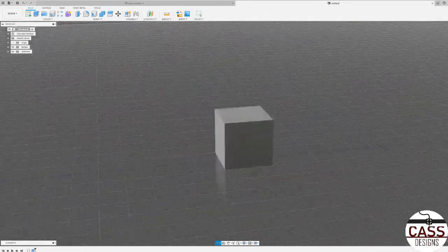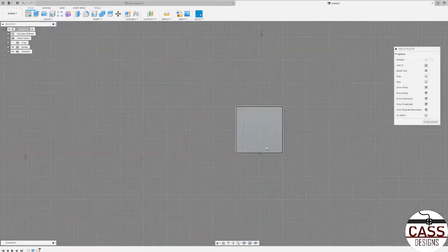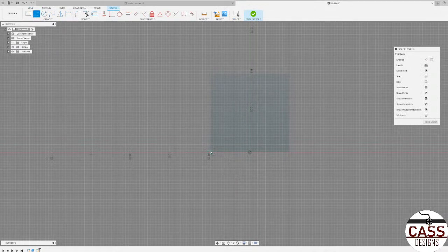So usually keycaps have angled sides. It's not perfectly perpendicular to the ground like this. So I'm going to create a sketch on this surface. And usually I would take dimensions and say, okay, this goes up this much. It's kind of flat. And from this point to the actual edge, I'll go up, and I'll start another line. I'll measure. I'll say it's about 0.1. And then I'll just make a triangular edge right here. And then here, since we know this is symmetric, this is where I can use the mirror tool again. I create another construction line right in the center of the object.